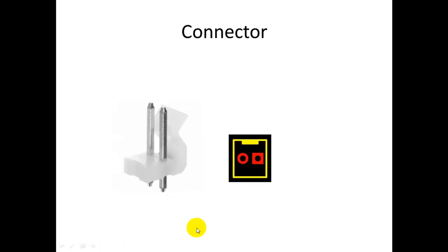Here is the footprint of another component. This is a connector. This is typically a connector with which you connect power to a circuit board, or sometimes input or output signals. This specific one consists of two pins. This is the top side of the connector, which will be sticking up from the top of the circuit board, and this is the bottom side, which will go through the circuit board and will be soldered on the bottom side, or the foil side, of the circuit board.